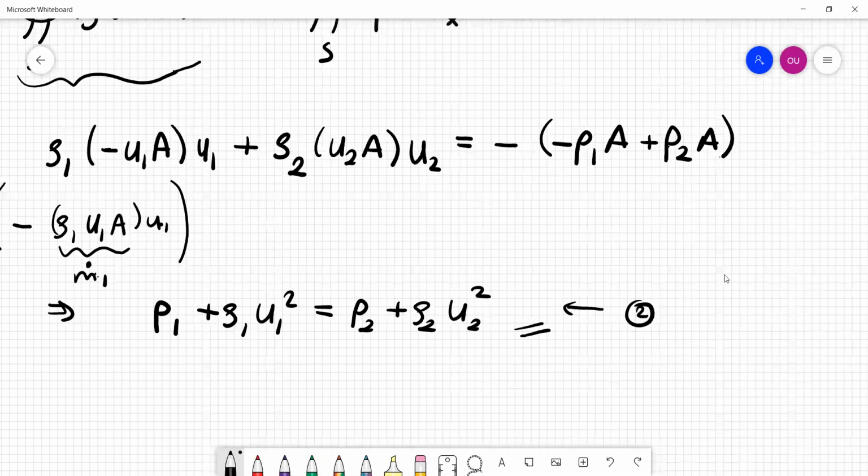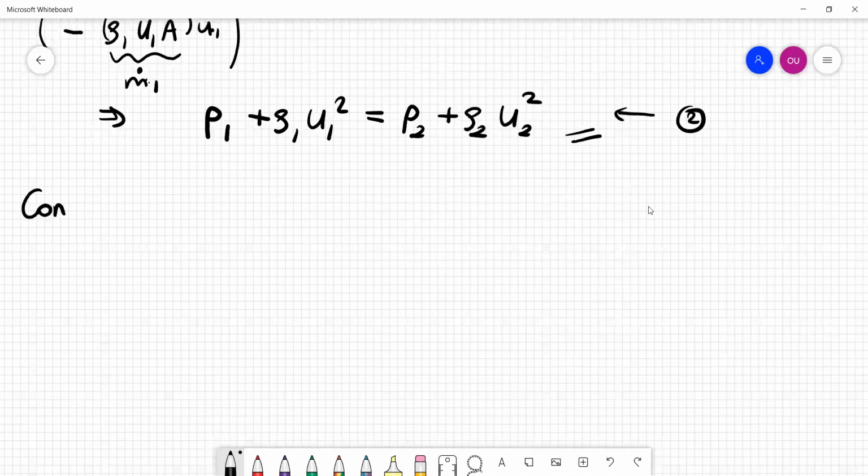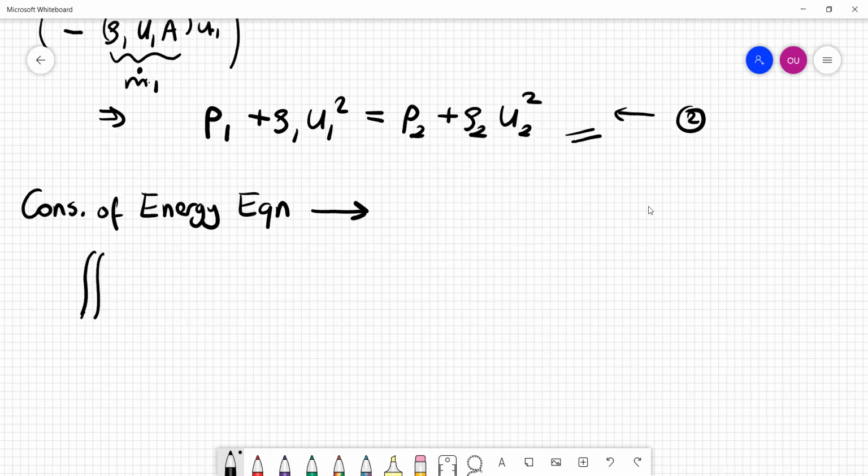So we also take into account the third conservation equation, which is the conservation of energy equation, as applied to this control volume situated around the shock wave. Again, it is a steady state process, meaning that we need to consider the outgoing energy and compare it to the incoming energy, and the balance should be related to whatever is changing the energy.